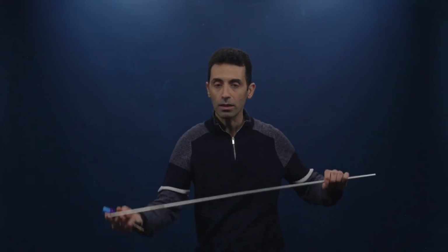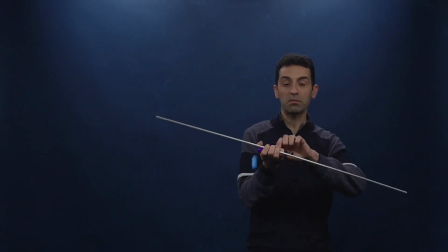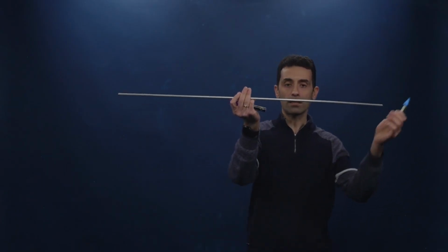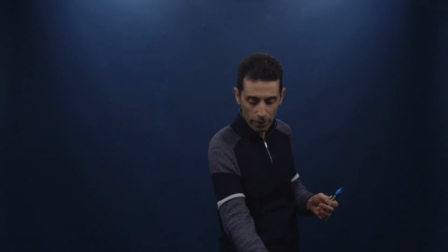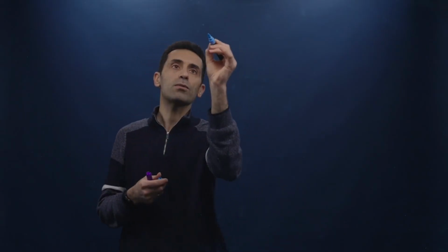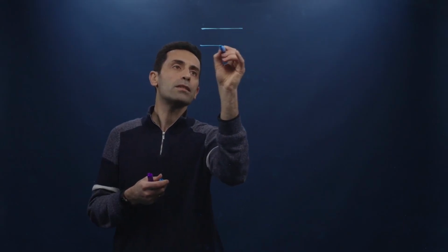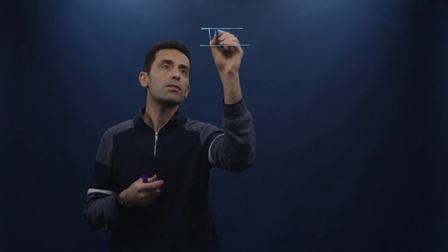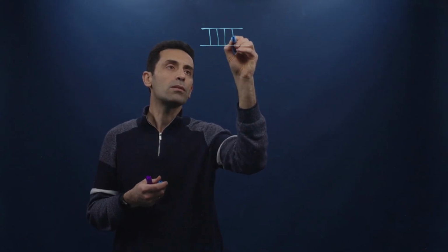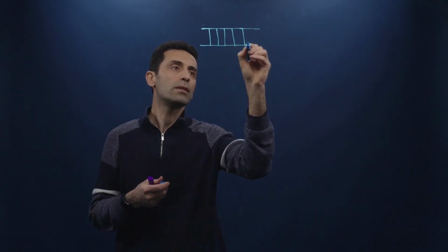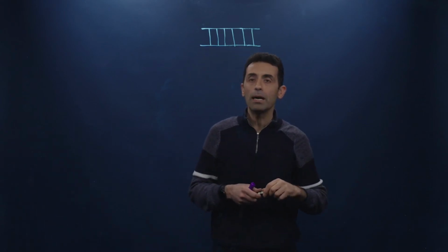Imagine if we had this rod and we want to develop a finite element model of this rod, and let's say we want to simulate that kind of impact that sends a wave across our rod. If I mesh this rod by using solid elements, and I'm just focusing on the central region of this rod, I'm just exaggerating that. Imagine this is the rod, and these are the solid elements that we have used. Well, of course, the aspect ratios are not great here, so we try to make the aspect ratio better if possible, but that's not the point.